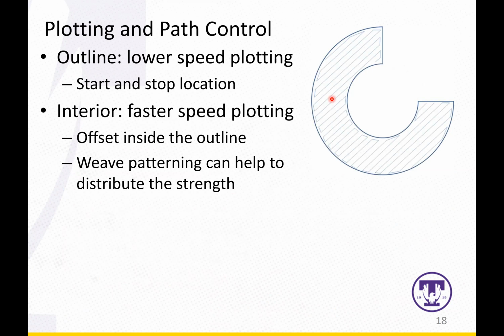As you can see here, these patterns will not touch this outline. Why? Because what the nozzle actually extrudes has a width, right? So that's why the tool path will look like this. But when the nozzle moves and extrudes following this tool path, these regions will be connected because there's a width for the material extruded onto the planar layer.